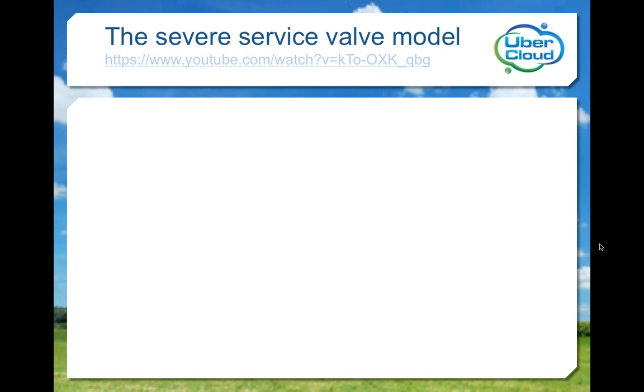My experience with industrial and oil patch control valves taught me to respect the amazing erosive magnitude of high-velocity fluid, laced with a little sand and a little water that will vaporize and then implode, causing cavitation damage when it strikes a surface. And when a control valve throttles down and velocity increases, the flow stream will try to blast its way through a tungsten carbide liner and valve body.